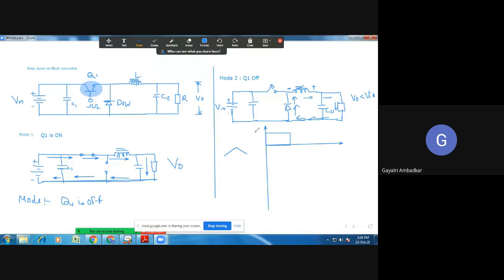So if I want to look at the voltage across the diode, I am getting high output voltage. When the switch was off, the diode becomes forward biased, so ideally there is zero voltage. Again, the cycle repeats.